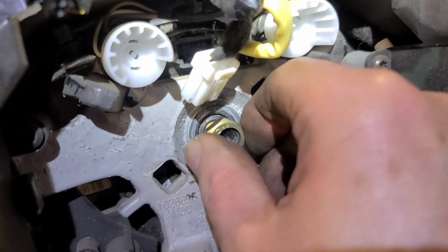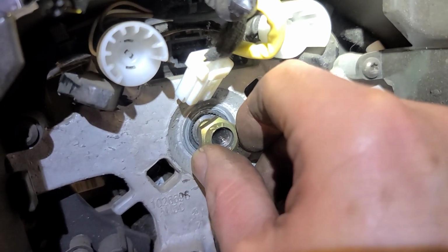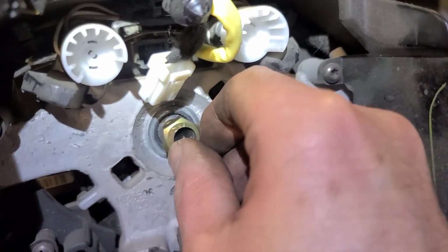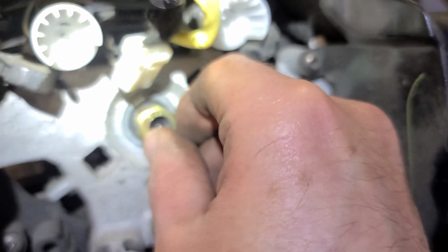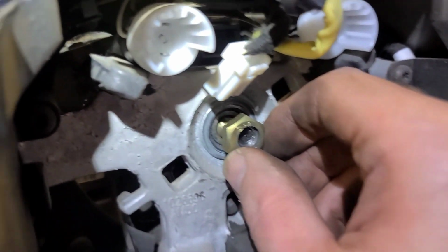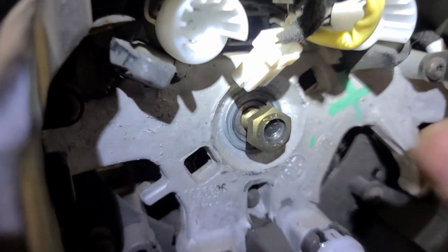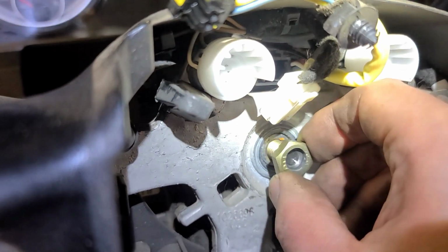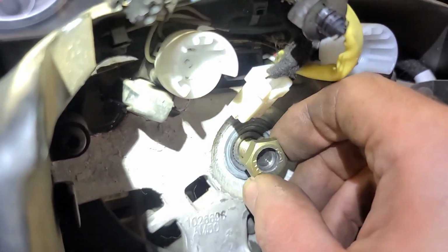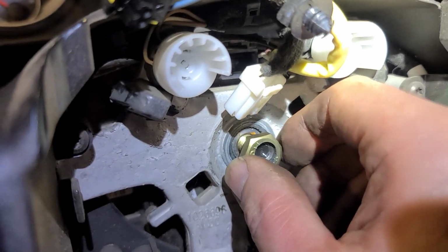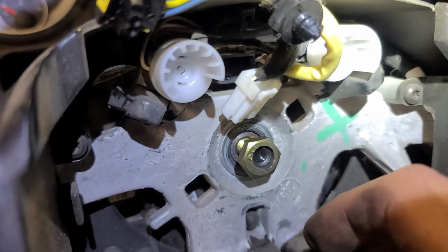I put a bolt in here with a center punch hole drilled in it, and I used the air hammer while I pulled up on the steering wheel, and it didn't budge. At least it doesn't look like it moved. I also marked it with a felt marker, just in case there's no master spline on it. I'm going to see if I can figure out some kind of puller.